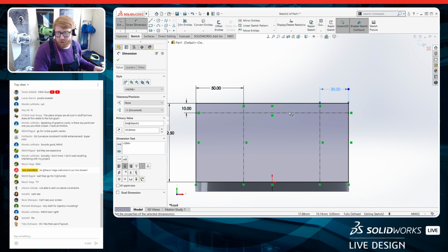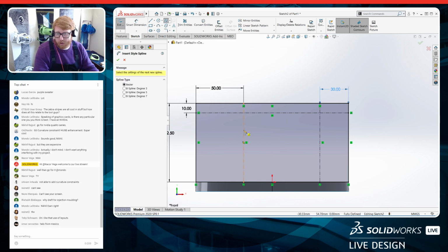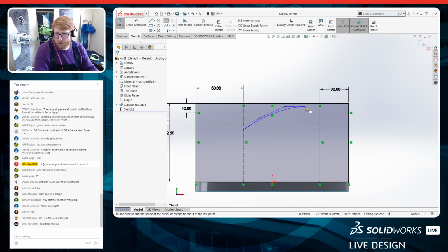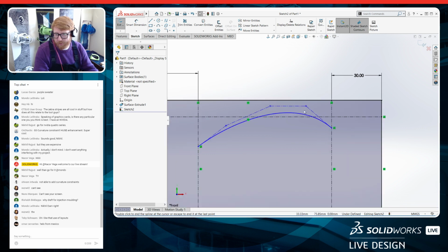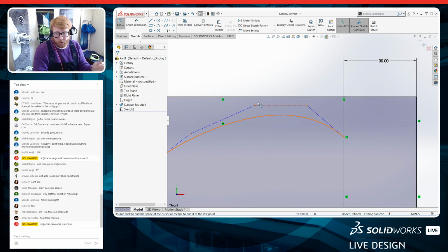So what I'm actually going to do is make sure that the top point of my spline here is at 10 below, which is going to be half of it, right? So kind of do something like this. And now I want the point of the spline to be here. Now, if I was using a regular spline, I could just put the point of the spline coincident to that line, but I can't do that because none of these points actually touch the curve, right?